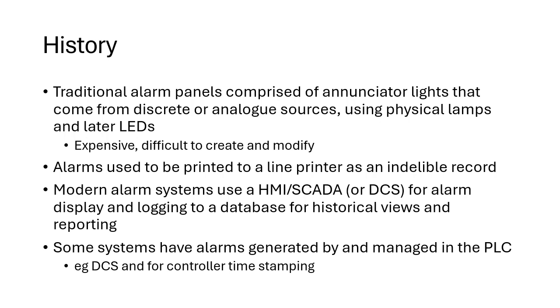For example, in electrical systems, if a circuit breaker trips, that can cause multiple alarms from downstream circuit breakers. So what you want to know is the first up alarm down to a level of maybe 1 millisecond. And the best way to do that is inside the controller. That can also help in distributed systems, where maybe you've got multiple client HMI SCADAs and you want to have a single view of the truth.